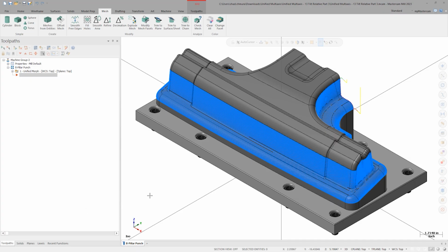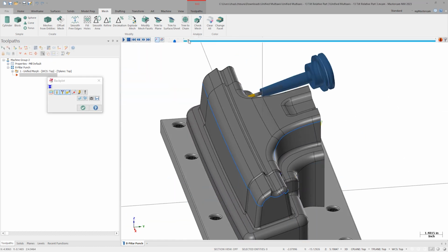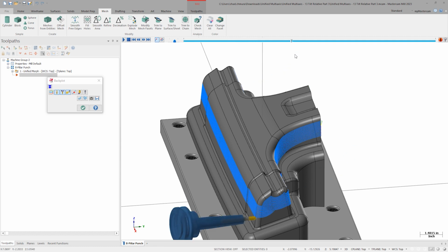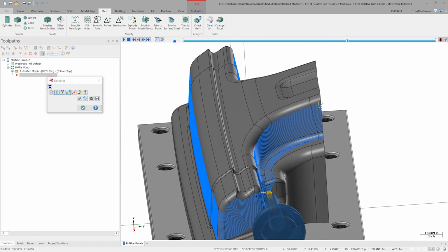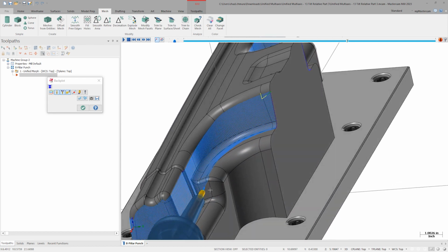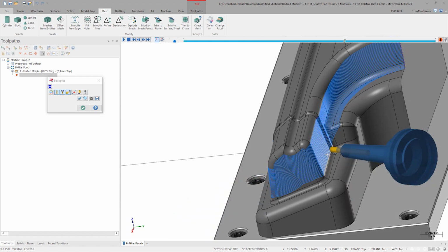Here we see the B-pillar punch part. The toolpath shown is a morph between two curves toolpath, and the tool axis control is currently set normal to the drive surfaces. Of course, as we backplot through this toolpath, we can see that it is full of collisions. At this point, we don't have many tool axis control options that can successfully clean out every problem area here.